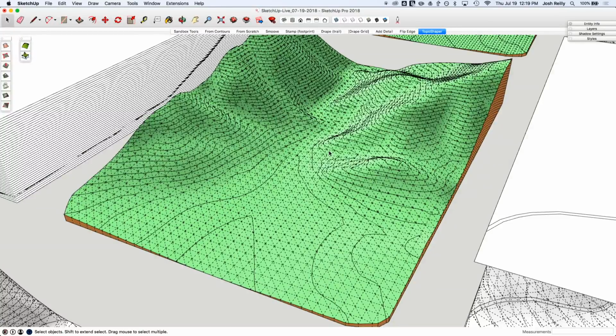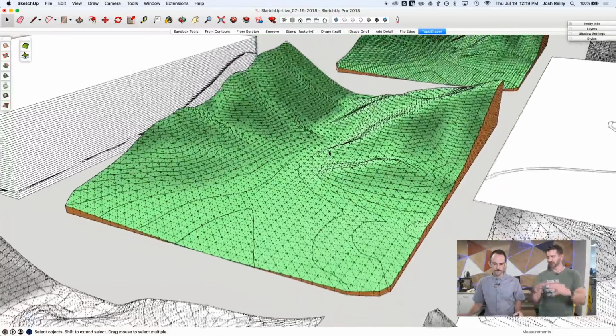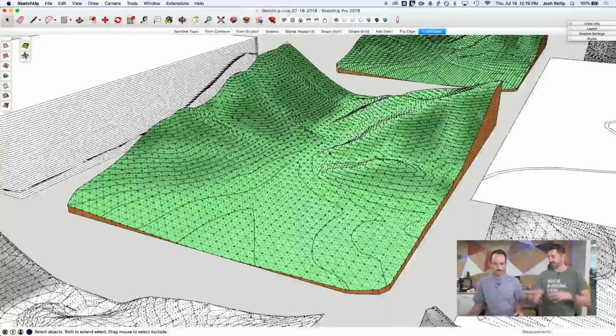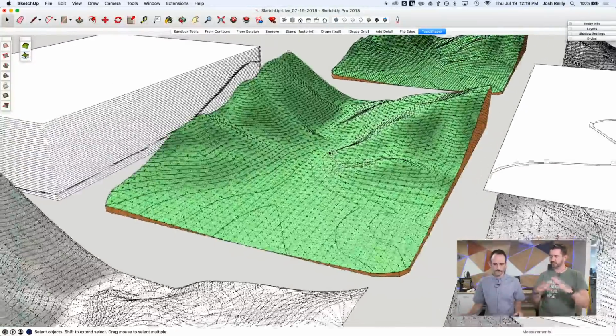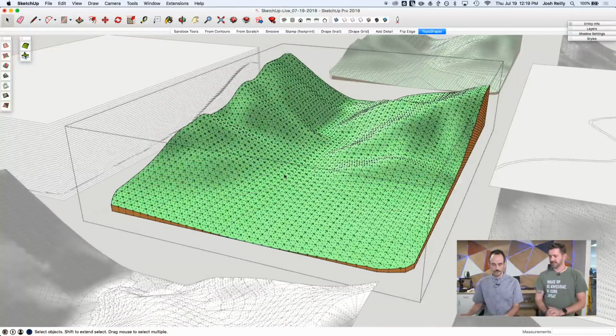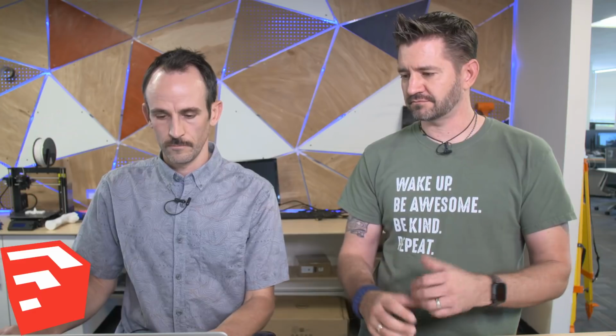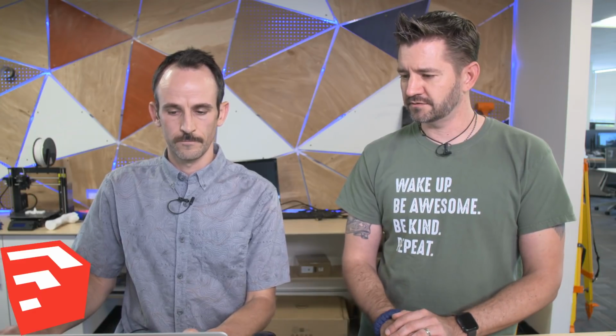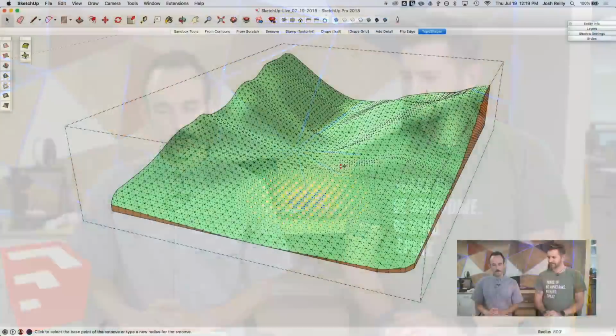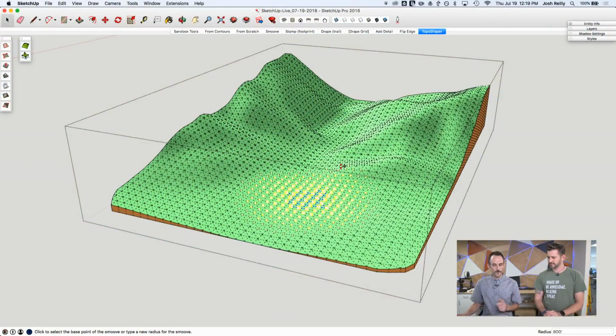Yeah, if you're going to come back in there in this example and raise up that low point in the Topo Shaper map here, just like you showed us with Smooth, you'd be able to bring up a nice smooth thing. Yeah. In the mesh that was created by Sandbox Tools, it'll actually create a weird geometry. And that brings up a good point I didn't say before about the Smooth tool: if you pre-select geometry, it's a different way of affecting that terrain, because it will act upon that selection a little bit differently.